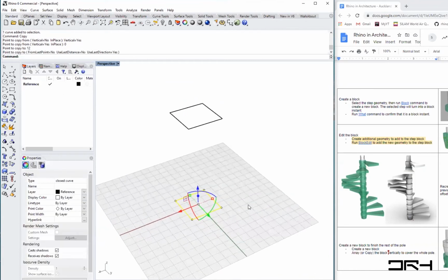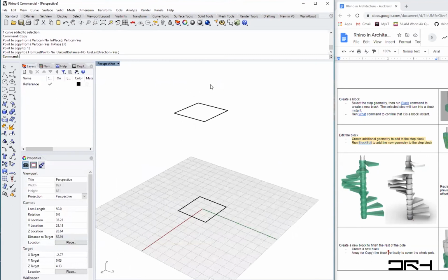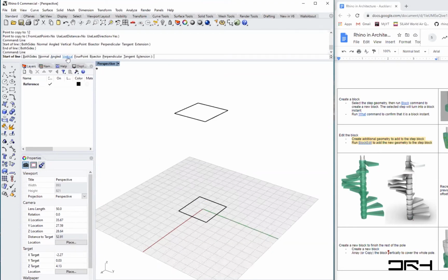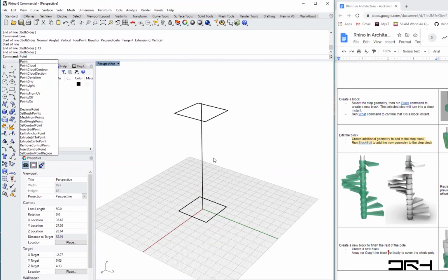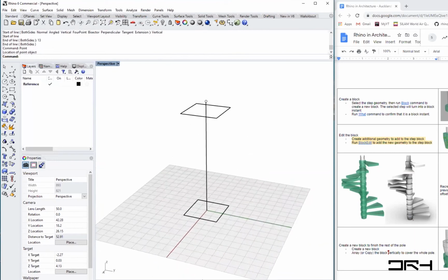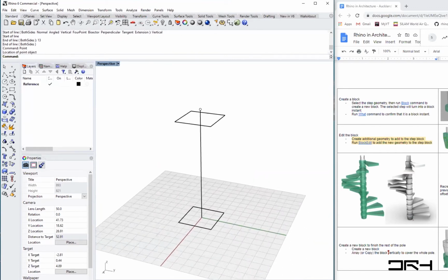If you recall, when we created the lighthouse, we extruded. Let me create a line here also from here, and let's create the line to be vertical from the center as a reference, and let's say it's 13 meters, and that's the end of it. And I'll create a point at the end, just creating some reference geometry here to generate my lighthouse. So if I use history, for example, I can do some parametric design of the lighthouse.